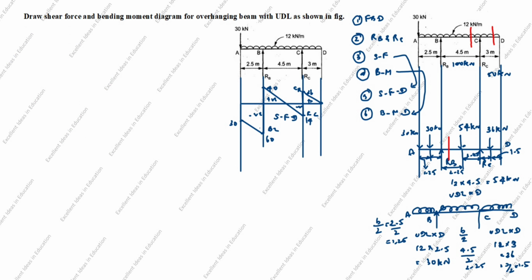Now we will do the bending moment calculation. Now we will see two rules. First rule is positive bending moment. It goes clockwise is positive on the left side. It goes anti-clockwise is positive on the right side. Positive bending moment. This is the first rule.